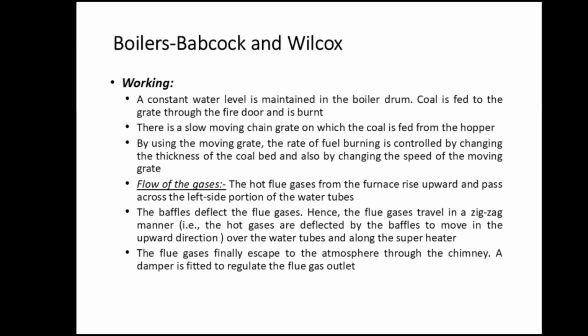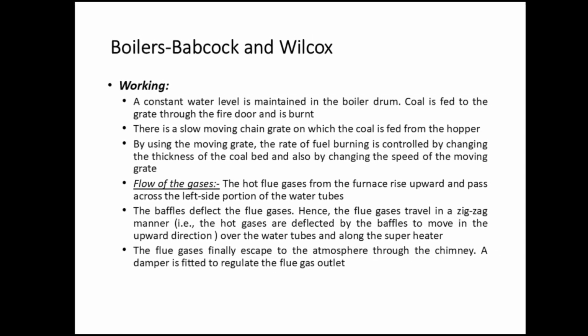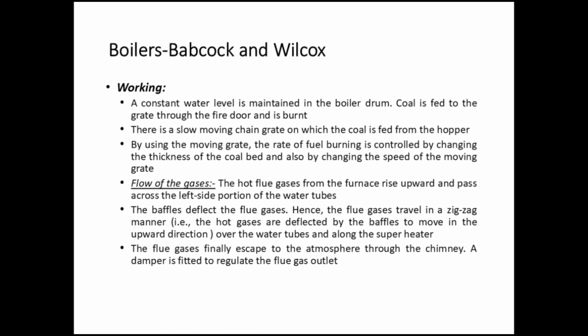Boilers. Babcock and Wilcox. Working. A constant water level is maintained in the boiler drum. Coal is fed to the grate through the fire door and is burnt. There is a slow moving chain grate on which the coal is fed from the hopper. By using the moving grate, the rate of fuel burning is controlled by changing the thickness of the coal bed and also by changing the speed of the moving grate.